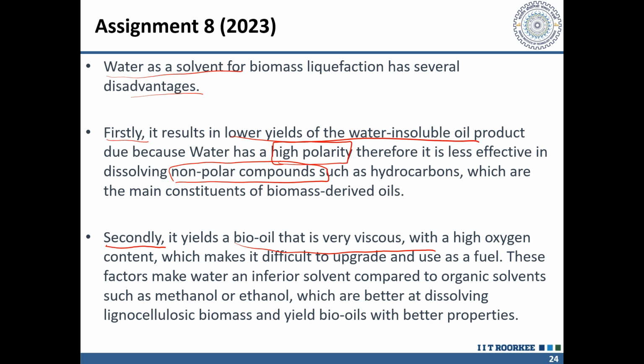Therefore water is not usually used, and we use some other polar compounds such as ethanol. Ethanol is also a polar compound, but it can dissolve some types of oil at very low concentration. It can dissolve oil at a low concentration, but by increasing the pressure and temperature, we can increase the solubility of oils in ethanol. Therefore, ethanol or butanol are used for the extraction process of oils at a higher temperature and higher pressures.